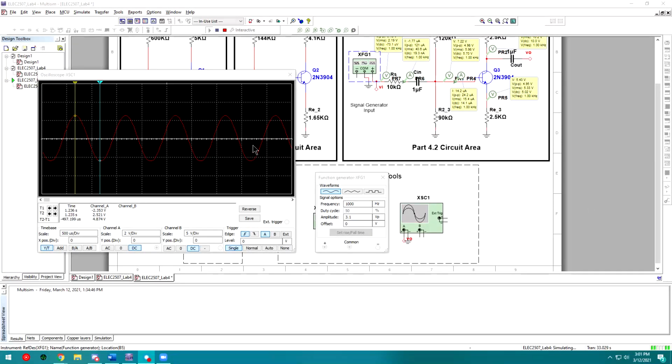So at this point, we're getting diminished gain, right? Because we're putting in more voltage than we're getting out. So it wants us to look for, again, the place where the tops now start to saturate and the amplifier is totally in saturation mode. So let's go ahead and increase this to 5 volts, see what happens. Run it normal. Still haven't clipped on the top. So let's go ahead to 7 volts.